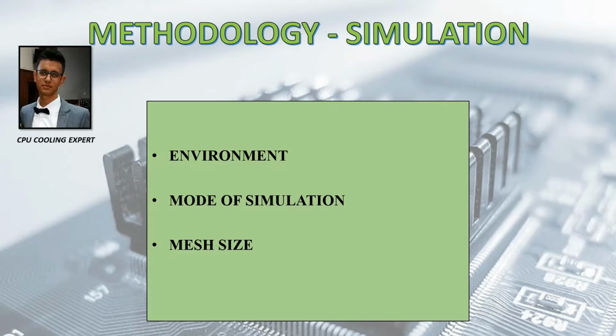In terms of simulation, the conjugate heat transfer simulation was used because it is capable of simulating the interaction between fluids and solids well. Using a mesh value higher than 3 was very time consuming. The validation produced pleasing results with this value, so we used the same value to run both simulations.